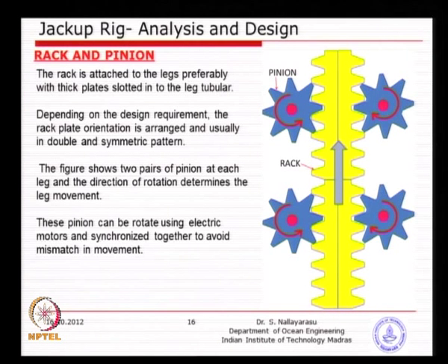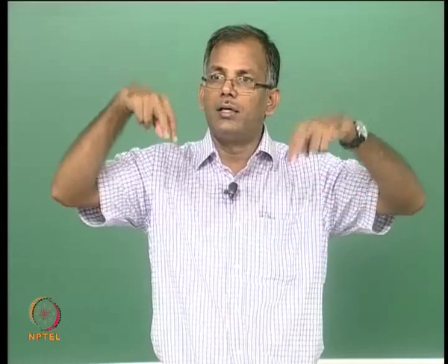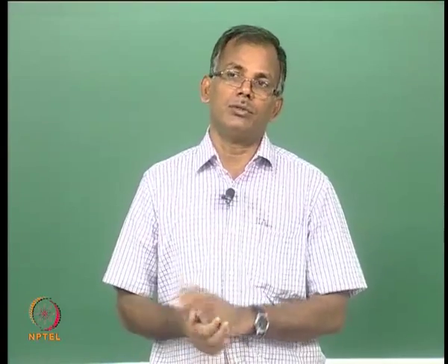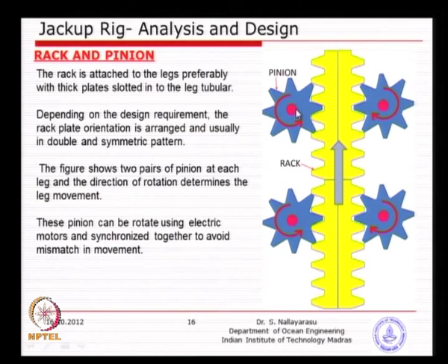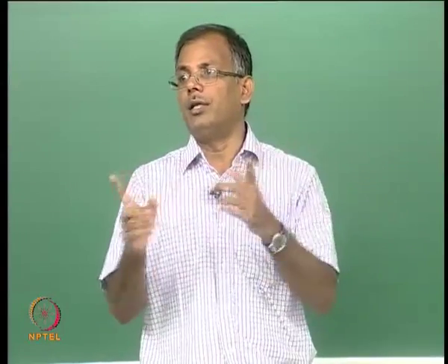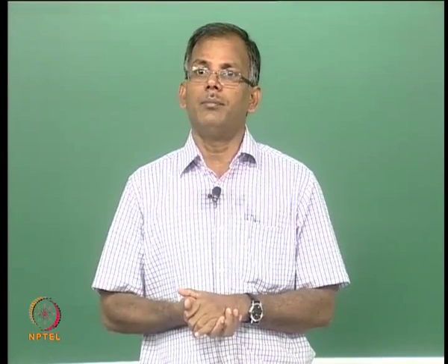move up or move down. Vice versa, when the hull is floating, legs will be freely moving up and down. When the legs are touching the seabed and having sufficient reaction, then you can actually move the hull upwards or downwards. So, it depends on which situation, but in both situations these pinion arrangements will be attached to electric drives, which can rotate and move upwards. So, the main important aspect in here is the synchronization of all the electric devices and all the operations to be at one time together.